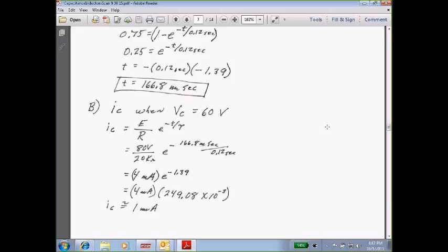We also use capacitors a lot for motor starting and motor controls. If you've got a heavy load, we use a capacitor start motor, which shifts the phase, which gives you higher starting torque to get the motor started and running. And then once you get it running up to speed, through a centrifugal switch, a mechanism of some type, the capacitor actually drops out of the circuit, and then you've just got your applied voltage.